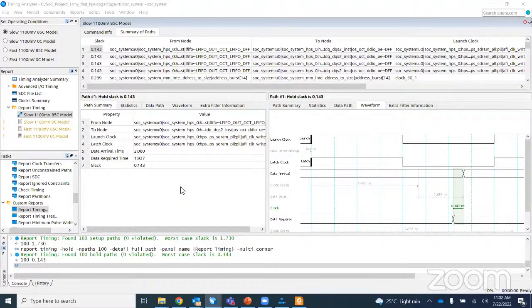We generated the HDL. We instantiated the design in the Quartus Prime design software. We performed analysis and elaboration, compiling the design. And we also have seen what is available in the FSM, finite state machine. We also have seen timing. So the only step we are not doing is implementing the design onto the board. Other than that, all the steps required from yesterday's discussion, we have done today.